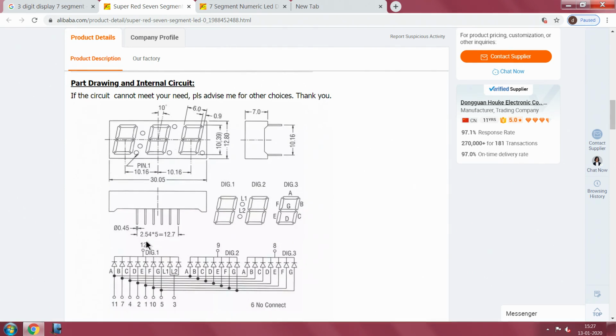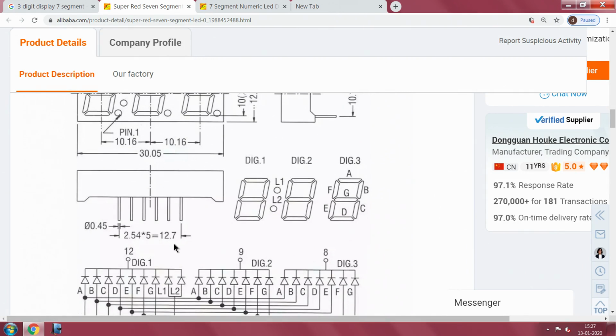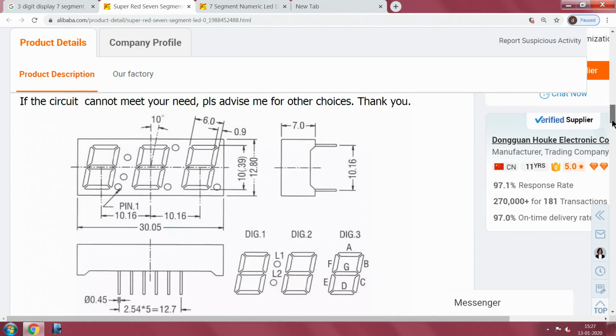If you remember, I told you earlier that 0.1 inch is the standard; this pin spacing typically follows 0.1 inches, which is nothing but 2.54 mm. And the way even these case dimensions are created, if you follow the standard way of mounting it, whatever the spacing is here, the next half pitch is here. So, you can stack them horizontally, and when you stack them horizontally, they read well without any problem.